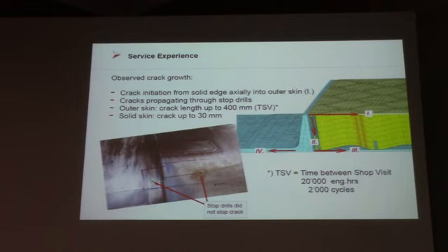To go back to this service experience, bad experience, in the sense that cracks were noticed in many components. In this case, you can see also in these two cases a good old way to stop the crack, but not successful in this case. Like in Liberty Bell, drilling the hole with the idea to reduce or to transform stress intensity to stress concentration, but it didn't work, as you can see. Probably because this is fatigue. In Liberty Bell it was just impact.